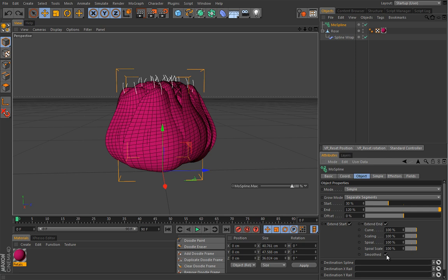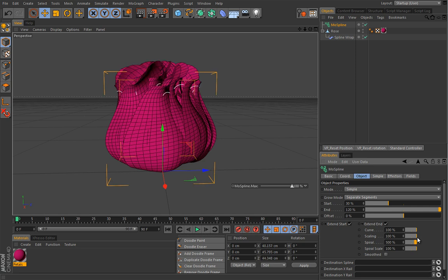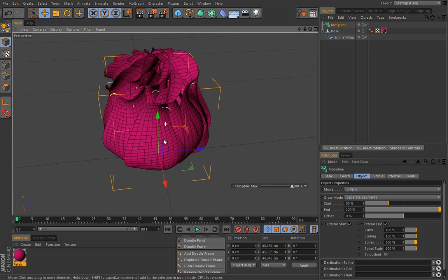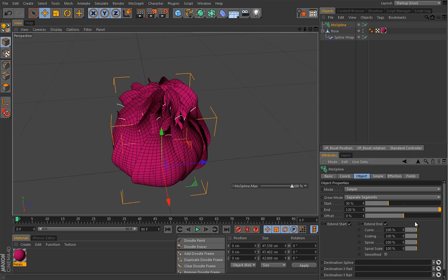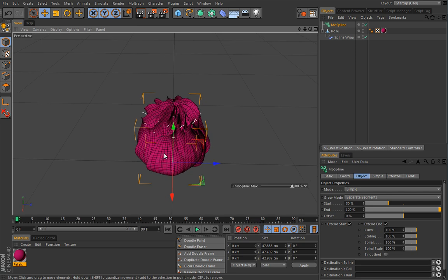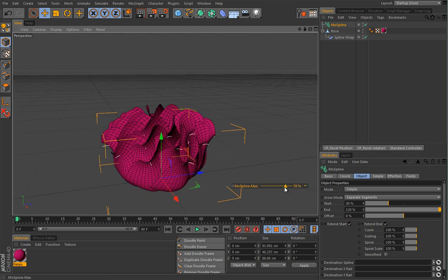Here under this extend, you can uncheck this smooth it, because it will really curve and accentuate all these effects. For example, if you enter something ludicrously high here, so let's say 500, you will get more of a spiraling effect. I hope that makes sense. So you can even leave it at 500. It really looks solid enough. Maybe even not. Let's go with the default 100 value. Now we pretty much have a solid